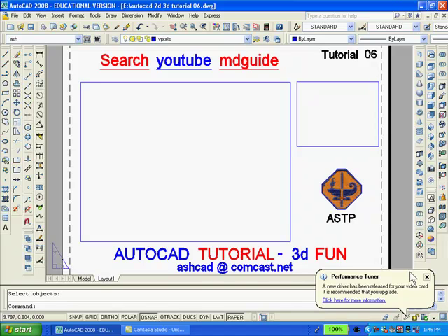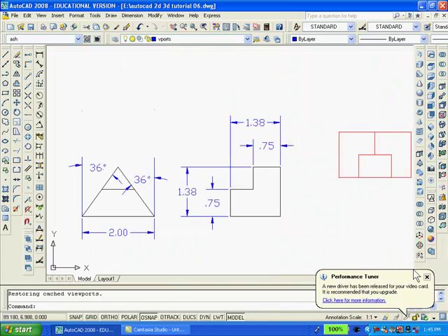To get into Model Space, I'll click the Model button. Please notice that both drawings still exist in Model Space even though they were erased in Paperspace. Now I'll erase all drawings from Model Space so that there will be room to redraw both the 2D and solid.